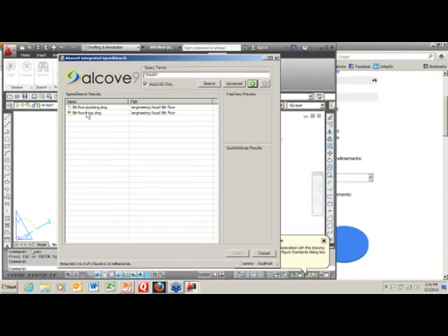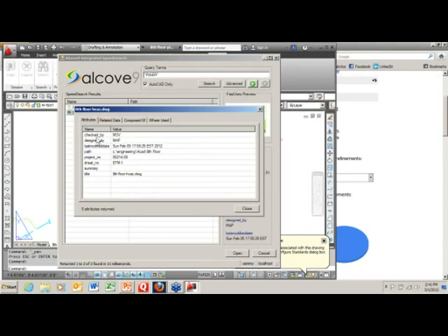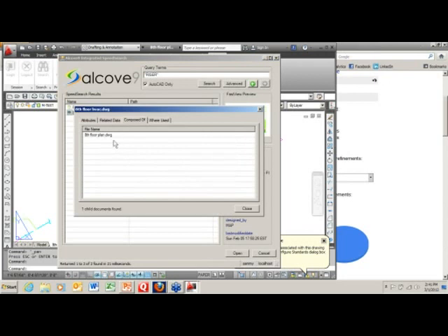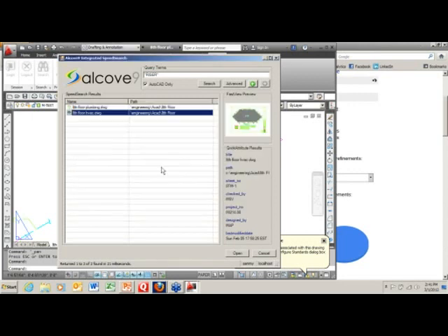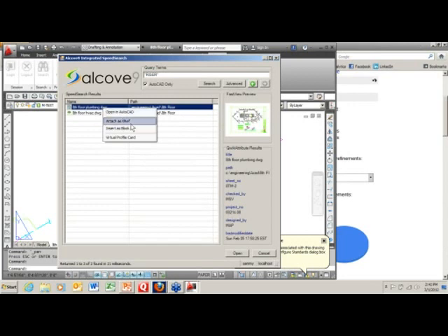The good thing about this also is that you can execute that virtual product profile card right from here. So before you open it, if you want to look at the attributes, related data, composed of, that in Autodesk terminology is called the XREFs. So you can look for your XREFs right in here. You can look at where it's being used also right there without even having to open the file, so you can further determine if that's what you're looking for or not. You can attach it as an xref also inside your current drawing, or insert it as a block if you choose so.